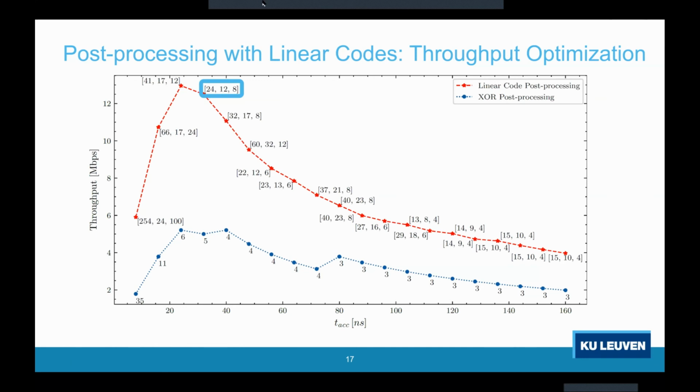Thank you for the opportunity. I want to ask about the cryptography side of this scheme. For a TRNG, you should test your random numbers with standard tests like NIST SP 800-22. As far as I followed your presentation, I didn't see your test with NIST SP 800-22. You just tested with NIST SP 800-90B for the entropy source.